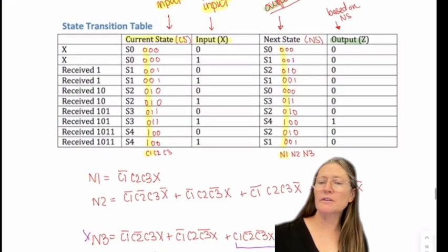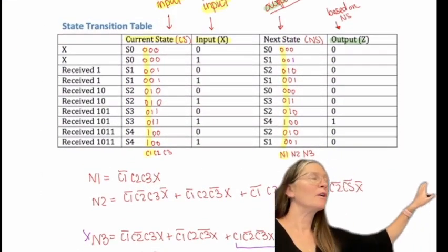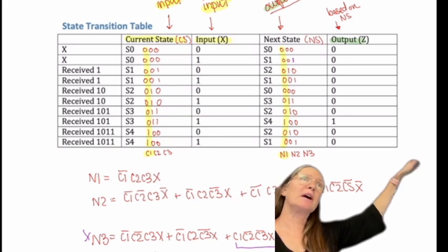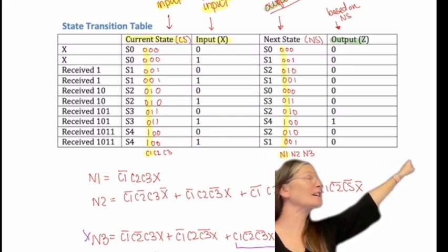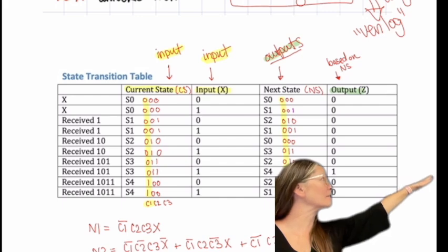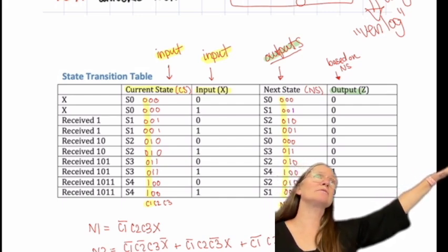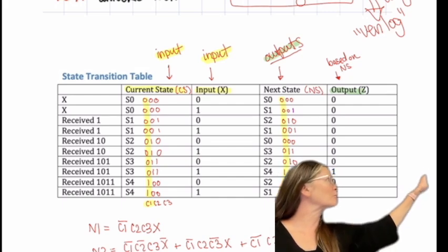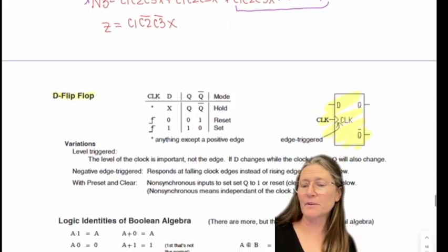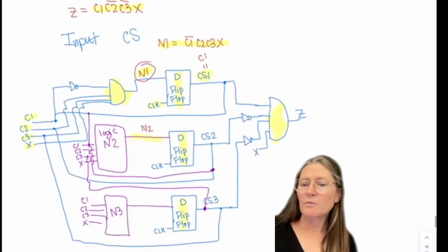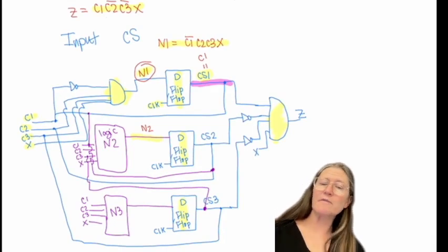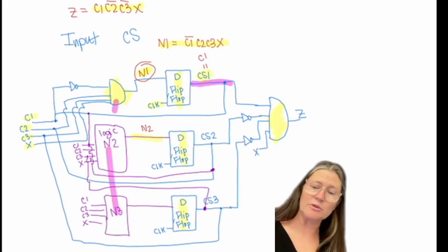When we code the actual table, we used a binary representation for the states. And the binary representation then starts to take the input as that current state. And depending on your current state, the output is your next state. And so we use logic to get from the current state to the next state, and then the flip-flop moves us from, so this is your current state, and it will get fed back into the system for the digital logic, which was here.